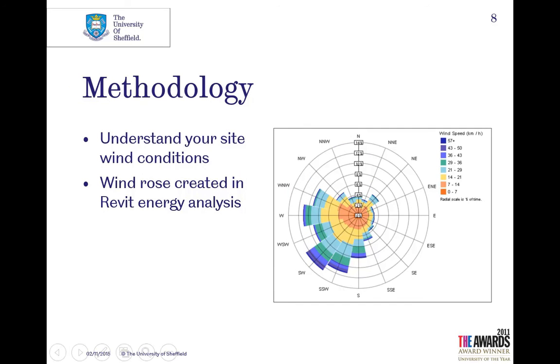It also depends on your site. Because of that wind funneling effect, where the wind gets blown between buildings, if your site has some particular narrow points between buildings, you might say, right, let's point the wind at that narrow point. Let's see what happens. You might look at your building entrance and say, let's point the wind at the building entrance and see what we're getting from that. So that's why I said you have to sample. You need to look at your wind conditions, look at your site, and you have to perform multiple samples. But it is, of course, quite quick to do that.